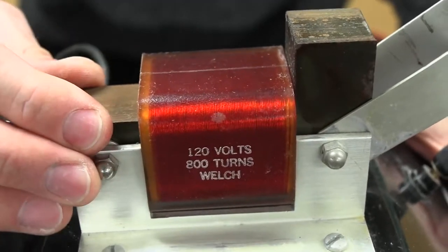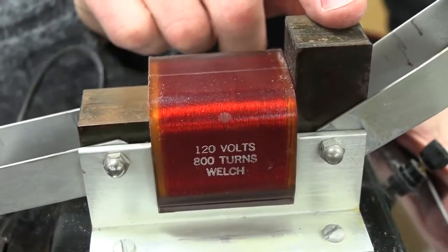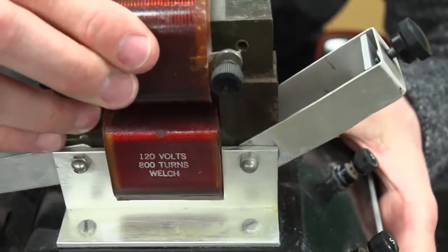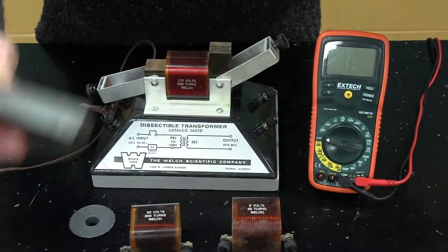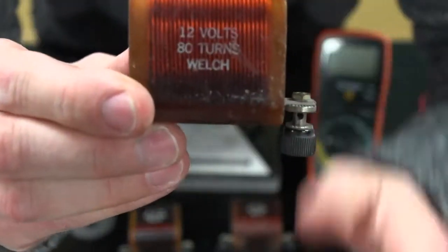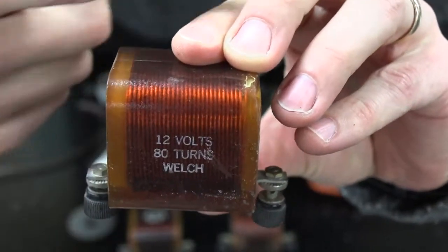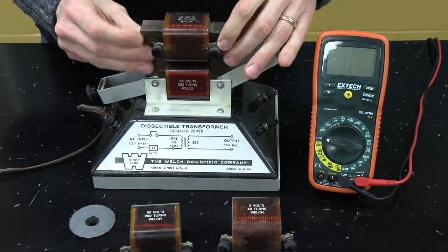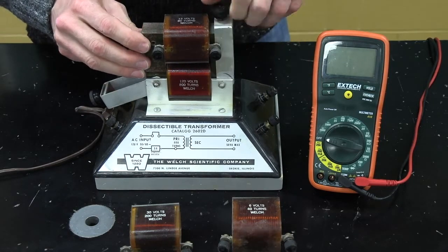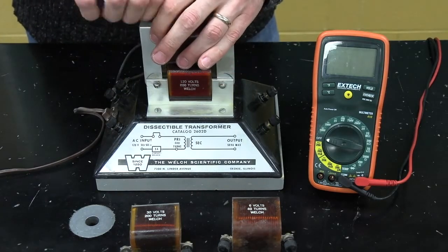It's around this iron so that the magnetic field that's going to oscillate in this alternating current will be going through this iron bar, and then we're going to connect it here so that the magnetic field gets piped up, in a sense, to this second coil. This coil says 12 volts, and it only has 80 turns. So the wire, instead of going 800 times around, only goes 80 times around. When I put it like this, I'm linking these two coils magnetically, kind of like those two solenoids I had earlier, but this is a more efficient linking of the two coils.